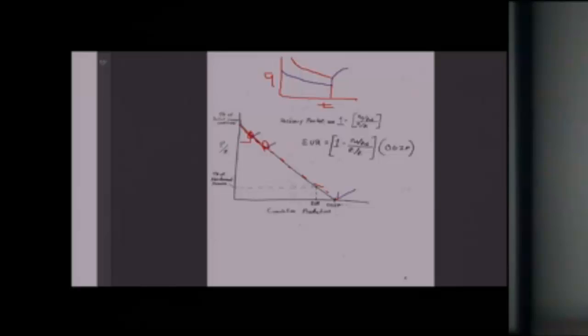So this is frequently done. A new well, I've logged it, I produced it for a while, I capture a couple more pressures, I know the gas in place, I can now back calculate the drainage area.